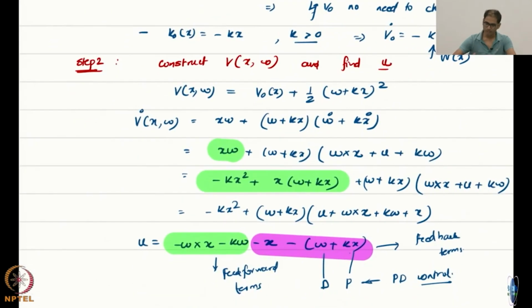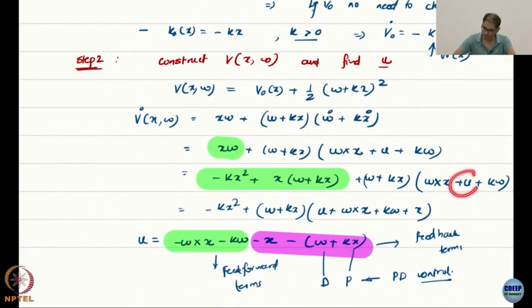Once we had that, we just kept taking derivatives and the control showed up, right? And once the control shows up here, we already know that this V is a CLF. We don't have to verify it again for every particular case. Either at this stage you can use the universal controller, which, like I said, is a more complicated formula, which is why you might want to do something different. So we do a Lyapunov reshaping type of thing, okay? You essentially choose U so that this whole thing becomes negative definite, okay? And we took a few guesses, and we basically cancelled these terms, and then you introduced a good term, right?